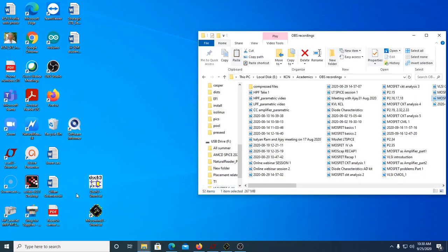Now we'll see how to write the schematic for digital VLSI circuits. Okay, let us start with a very simple inverter where I'm supposed to have one NMOS and one PMOS. So this is the Microwind tool. In Microwind we have this digital schematic. Let me just start with one NMOS. The other is a PMOS transistor. Let me just place it here.